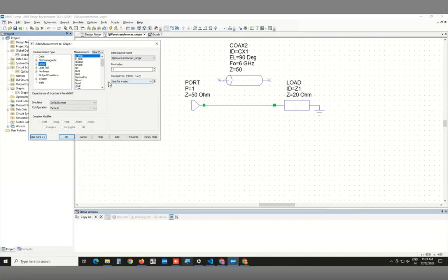In the exam problem 2, I had given one example of a nonlinear one, which I will go through after the first problem. But otherwise, pretty much everything is in this linear one. And even under linear, you go to port parameters, which are the scattering and other types of parameters. There also you just choose S. So this is the default setting anyway, and this is what comes.